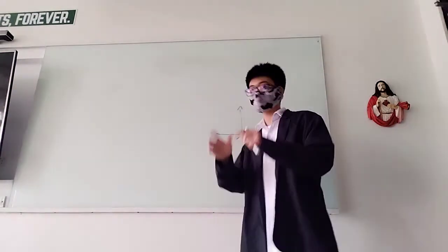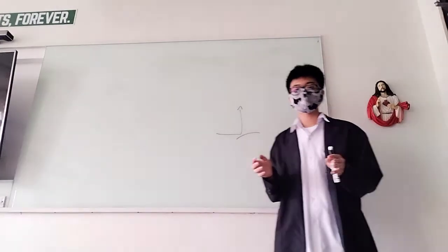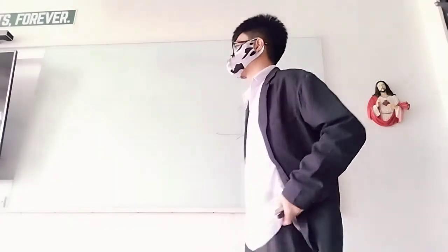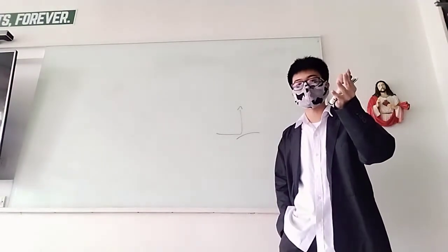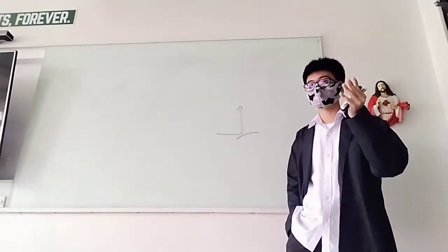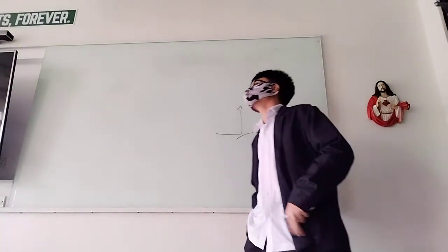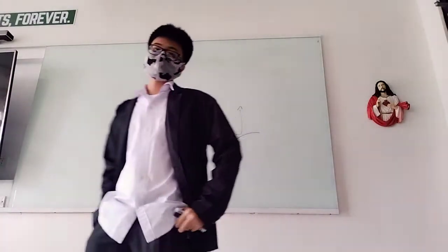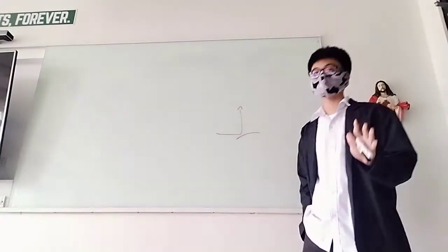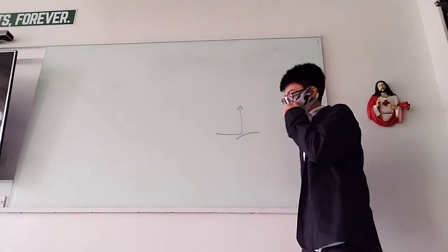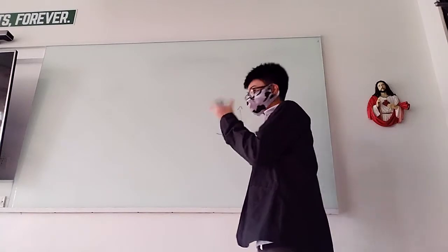You need to evenly distribute the pressure of your air, or your pressurized material, equally around the shape, the volume or the surface. That prevents rupture, and it equally stresses the material on all parts. That's the reason why it's cylindrical in nature.